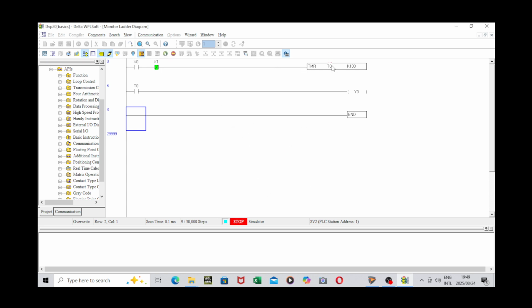You must check this timer. It will start to count when we energize X0. So we set on, it's like you're pressing your start button. Now we see your timer is counting. After the preset time, we should have our Y0 turn on. Let's check, and that's it.